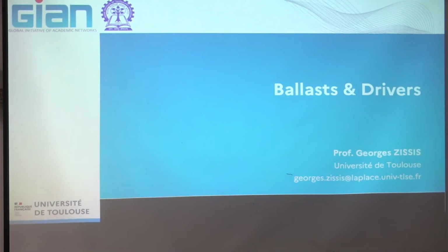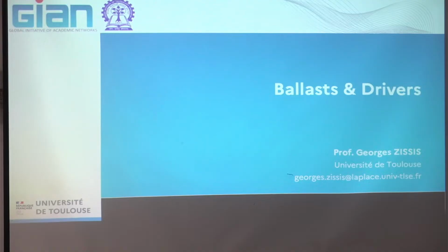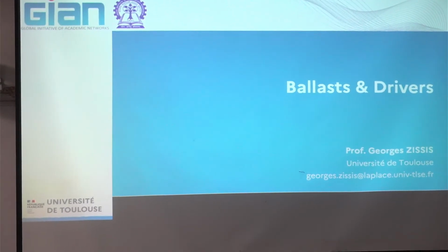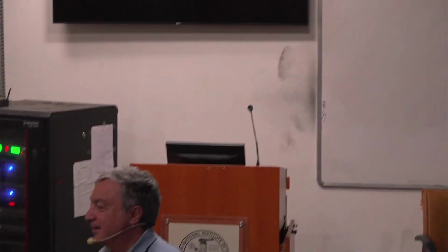The first talk will be on ballast and drivers. Does someone among you know what the difference between a ballast and a driver is? Pradium? No? Well, in fact, there isn't any kind of difference. Drivers are exclusively electronic devices. Ballast can be either electronic or ferromagnetic devices or any kind of passive devices also.